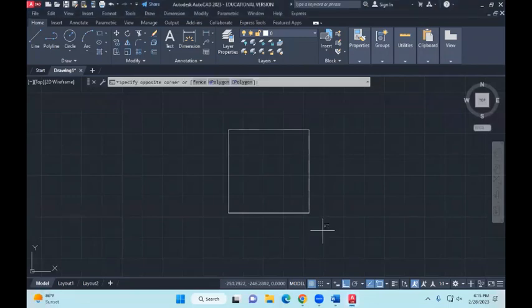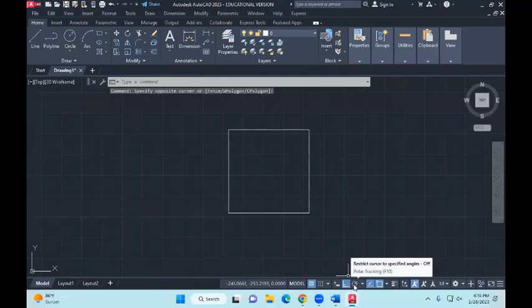So it does two things. Auto mode, if you have it on, allows you to move things at 90 degrees, and it allows you to draw at 90 degrees, or at right angles. That's auto mode. So the button beside the auto mode is what? Let's just try it out. There, it's called polar tracking. So we'll just click on that.